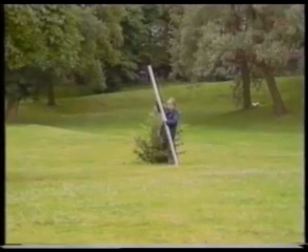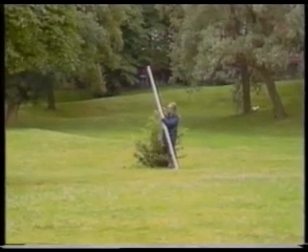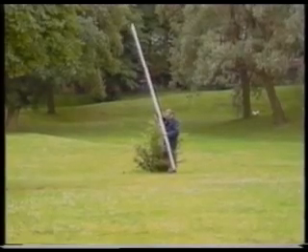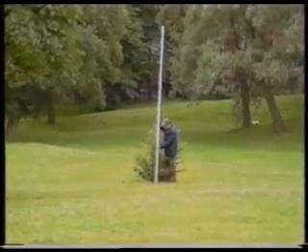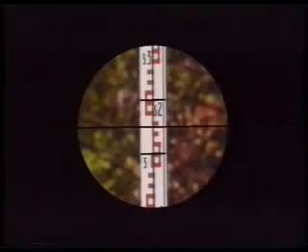And the person holding the staff keeps it as vertical as possible. It is not advisable to rock the staff as we do in leveling, since in stadia tachyometry it is read using all 3 hairs engraved on the diaphragm, and this is not easy to do if the staff is rocking. The top and bottom hairs are known as the stadia hairs, and give this technique its name.